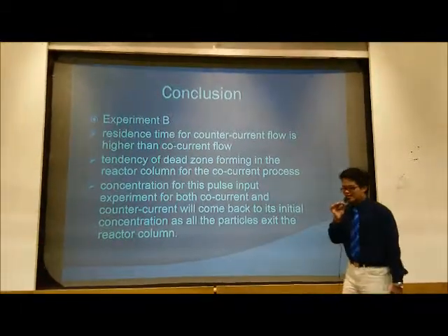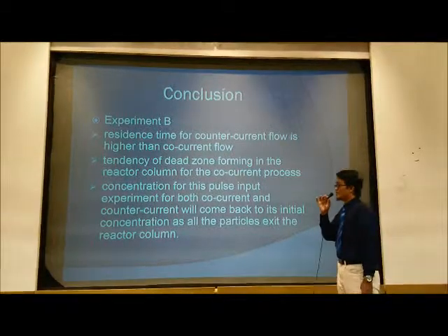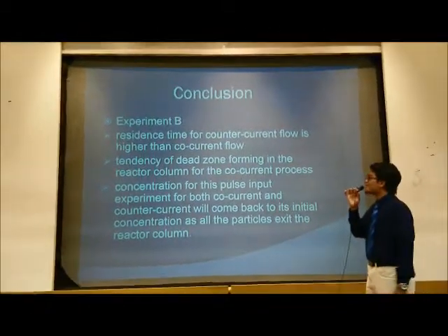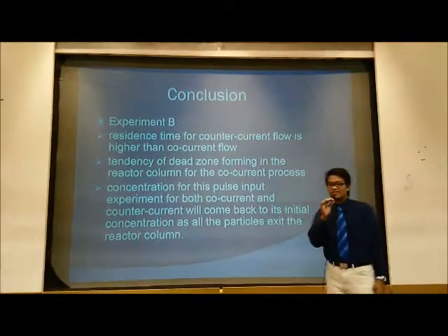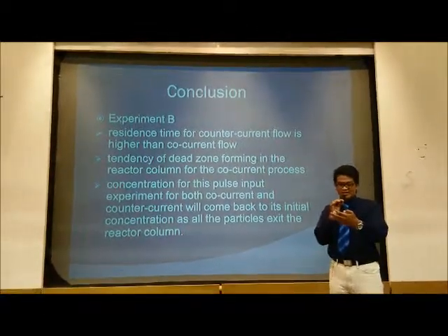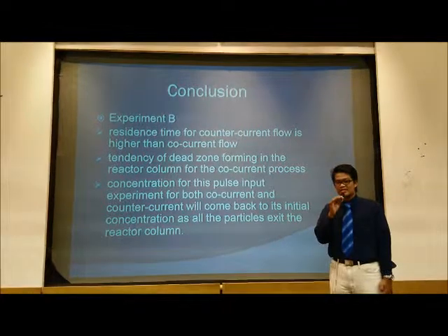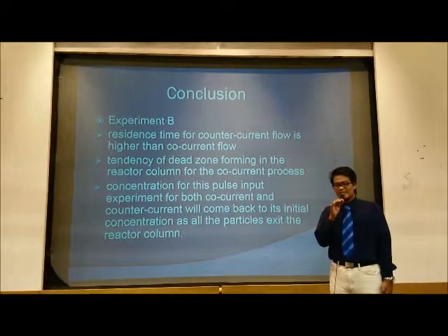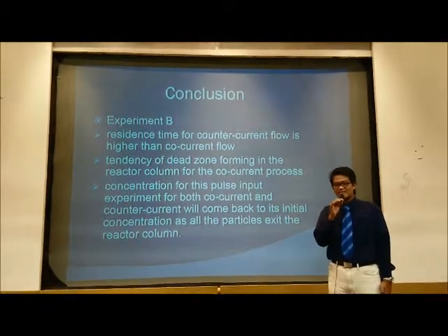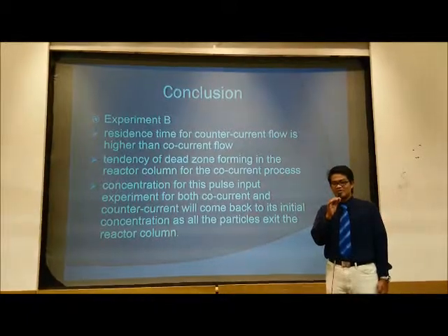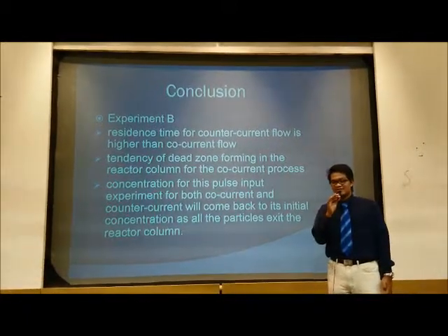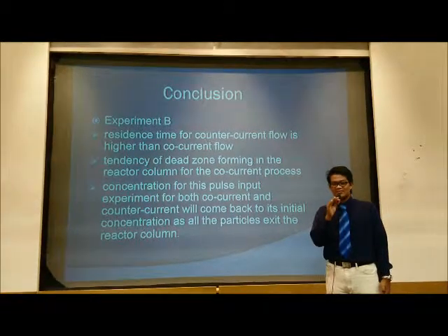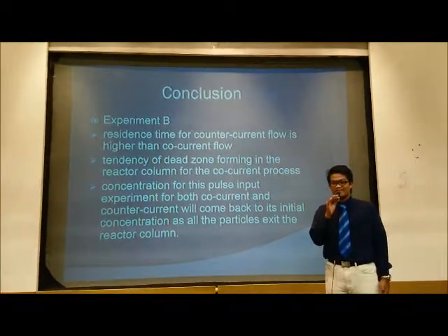And for experiment B, our first point is that the residence time for counter-current flow is higher than co-current flow. And why does this happen? This actually supports the theory that a longer time is needed for sodium chloride to stay in the reactor column in counter-current flow compared to the co-current flow.